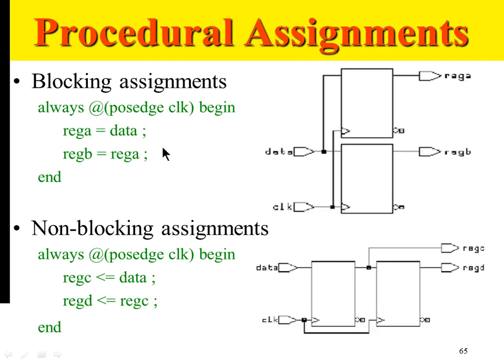So why are you using Verilog as a language? You want to design hardware. So if in real life hardware this delay is going to be present, that delay has to be modeled in Verilog as a hardware description language. If I use blocking assignments, then that delay is not being modeled here. I'm bypassing, short-circuiting that delay. But if I use non-blocking assignments, I make sure that the delay which will happen in hardware is represented properly in my Verilog code, even at simulation level.